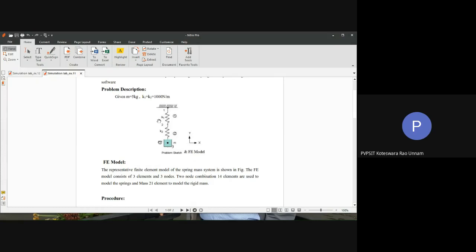But here in our software, whatever nodes we created will have 2 degrees of freedom or maybe 3 degrees of freedom. Therefore, whatever degrees of freedom are unnecessary, we need to eliminate them. To eliminate them, we can do that while defining the behavior of the spring. Since I'm defining the spring using 2 nodes here, I can define its behavior also.